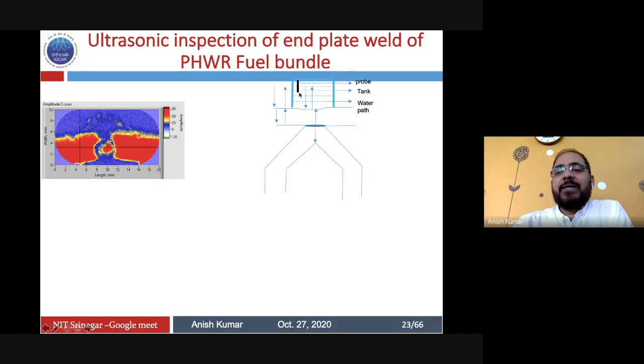And if you take this plate and generate the C-scan, what you see here is reflection from the interface, like this here. In this place, you get again reflection from this plate itself, high amplitude reflection here. Near this area, the sound beam goes in some other direction. It does not come back. But in the center, you get reflected or diffracted signal from here, and you see again the high amplitude. Red is the high amplitude, and blue is low amplitude.